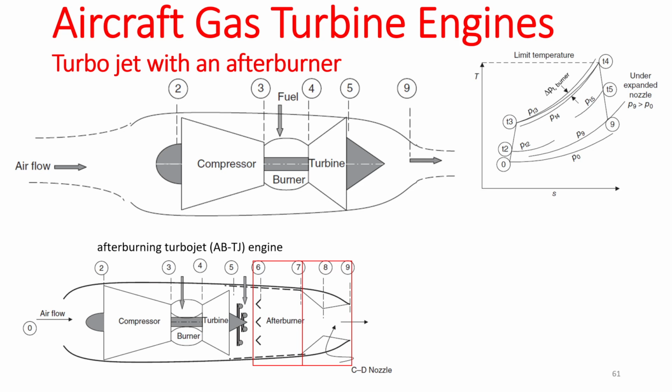Okay, so what does it mean for that convergent divergent nozzle? Think about it this way. Your afterburner is not always on. Afterburner is something you can turn on and turn off, and sometimes you need it to be turned off, right? So it must be adjustable. The convergent divergent nozzle area must be adjustable, which means that the choking area, the throat area, which you always design to have a choking condition, must be a variable area.